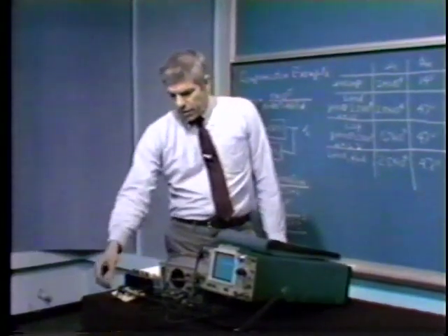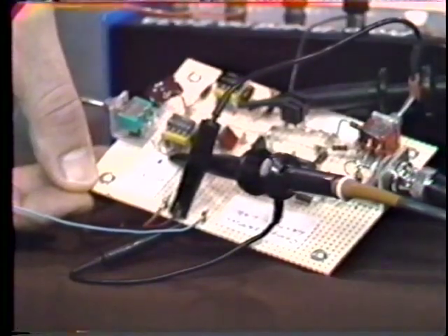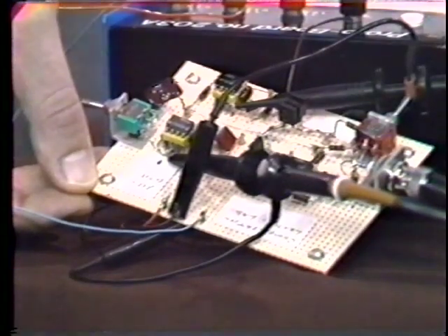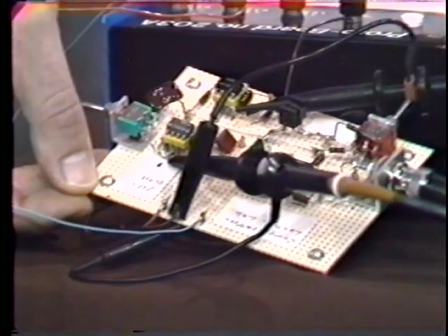Well, what I'd now like to do is look at the behavior of the system under these conditions. And what we have here is a little board that's effectively our pseudo amplifier. We actually make it up out of several operational amplifiers, as you can see. We have networks that fairly precisely locate the poles associated with our pseudo amplifier, the poles at omega equals 1 radian per second, at omega equals 10 to the 4th radians per second, and at omega equals 10 to the 5th radians per second.